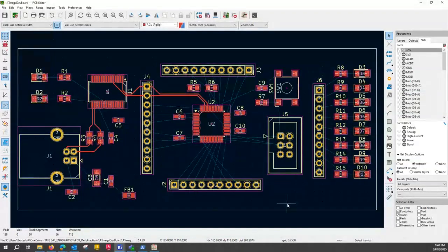Now, obviously, there will be some other tracks which may also be used as communication tracks. And what we're talking about is, all those pins, they connect to input-output pins from the micro. They go into those external pins. You may have a device plugged in and you may want to communicate with some reasonable speed there, which means, yeah, they're also high priority, but we don't know. So this takes priority. We just lay out our RxTX first, and then we do the best we can with all the other pins, which are input-output pins.